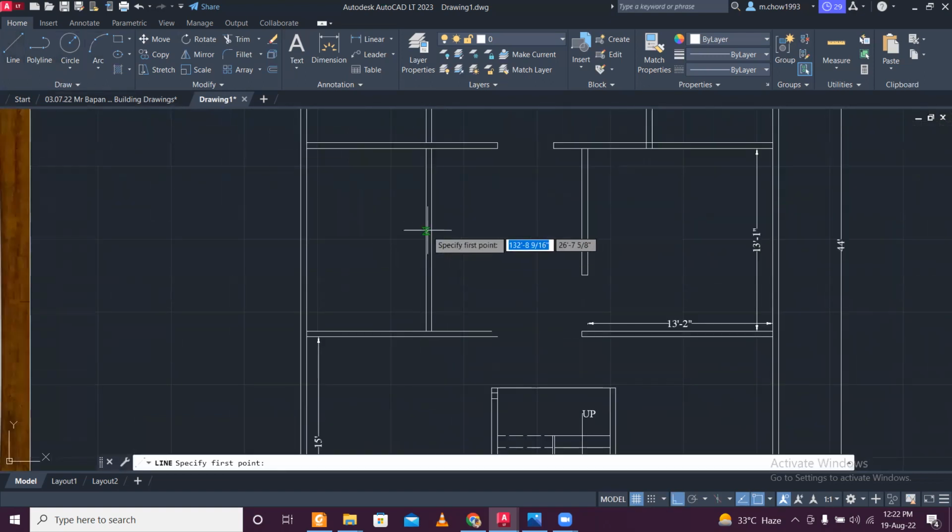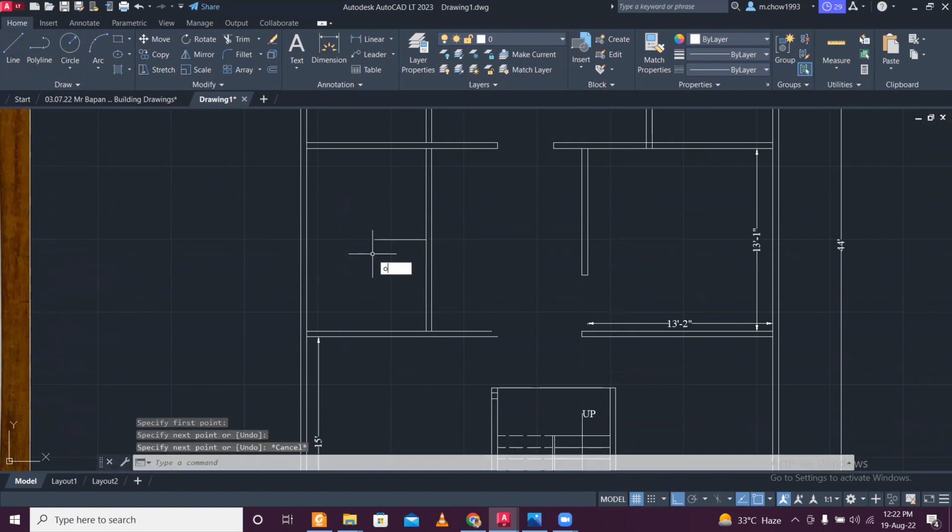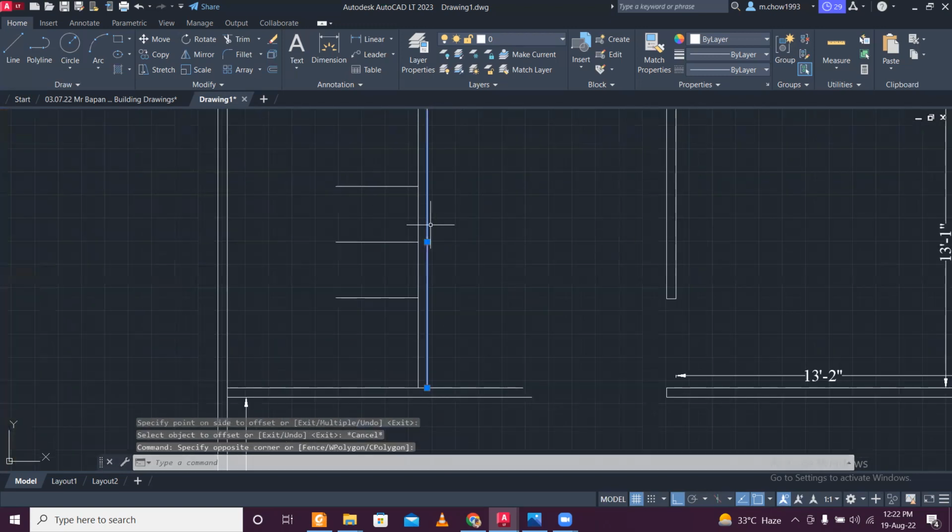So here, this is the midpoint. Let's keep a 6 feet wide opening, or 6 feet is too much, right? Let's keep a 5 feet wide opening. So I'll keep 2 feet 6 inches on both sides. 5 feet wide opening is my choice.